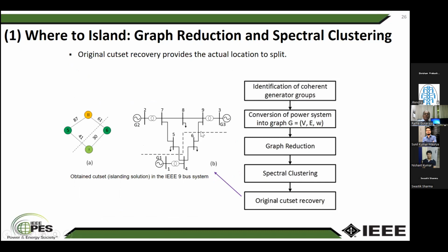So we'll have out of step relays on these portions of the line, and then we'll separate these two if a disturbance happens. Major disturbance, and because they are splitting as two coherent groups, the out of step relays are going to create an island. So this is going to be one island, and this is going to be the other island. So this is why I chose the 9-bus system. In terms of a schematic, it was easier to show it to you.